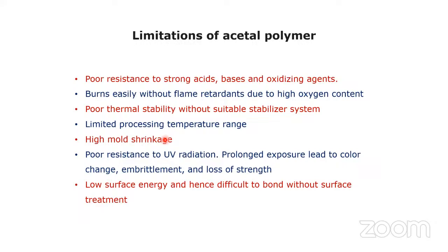Why is there high mold shrinkage in the polyacetal case? That was your question at that time. The reason is that, as we are continuously mentioning, it is a highly crystalline structure. So what is the nature of a crystalline structure in general? When your polymer, the polyacetal, is in a molten form, obviously your polymeric chains will have some movement.